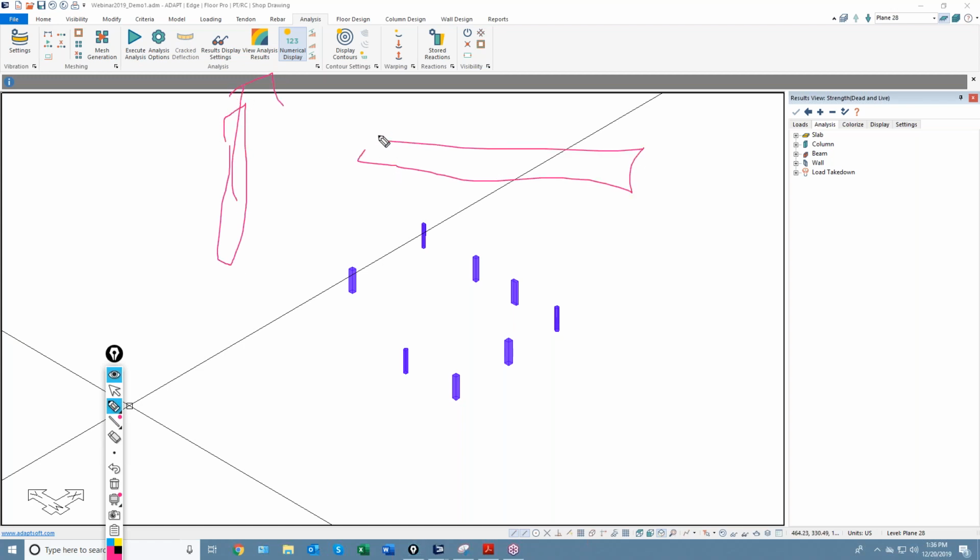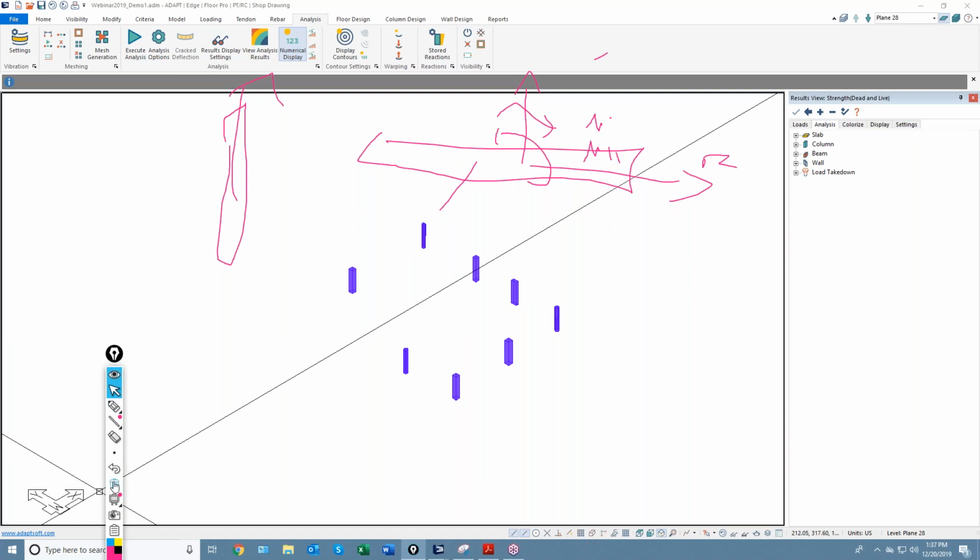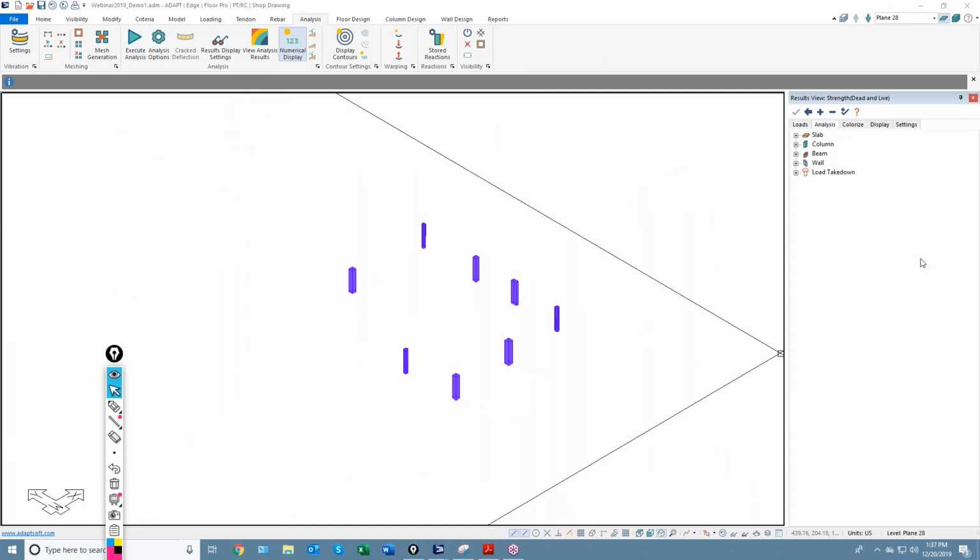So if this is a wall in plan, we have R. I'll do it this way. We have a wall. This is R, and this is S. If that wall rotates, the axes rotate with it. So bending about S, we have no modifier for that. I believe we have modifier M11 and M33, which is kind of about the Z axis. Steve, that's coming. That's something that we're aware of, and we need to add that in. So it's been documented as a priority item for global mode. I can't tell you when, but it has been documented.